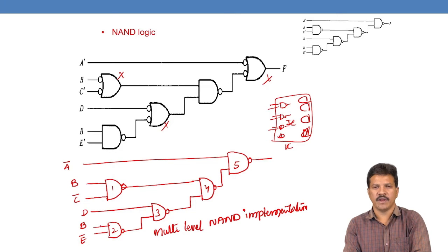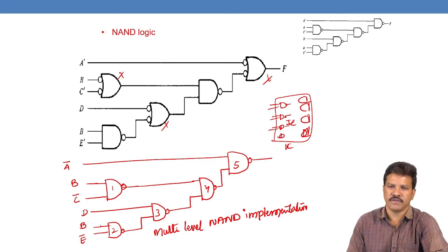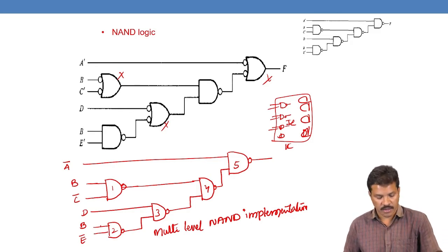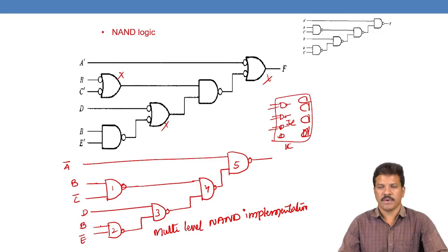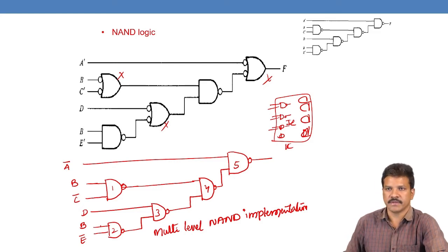When we implement any Boolean function, we can take a simple IC. If we require more NAND gates than the IC has, we can use another IC and connect both chips. That is the main advantage of NAND and NOR implementation: the diagrams will be easily implemented using integrated chips.